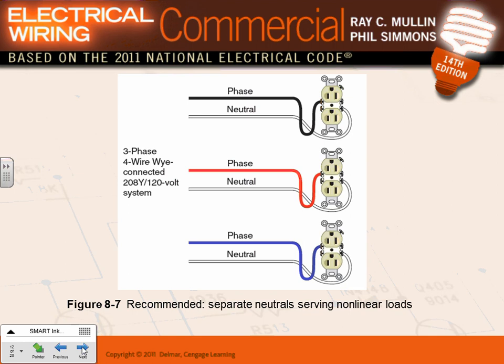So to eliminate the effect on the branch circuits, do you guys remember how we do that? We have a neutral with every phase. That's what you guys are doing with me, right? In this project, there are certain receptacles in that Revit project that require you to have a neutral with every circuit. Why? Because if you have 10 amps, they don't add up to 0 amps because there are harmonics on them. They might add up to 20 amps and overload the neutral. To solve the problem on a branch circuit like this, you just have a neutral with every phase. Can I have a thumbs up, Chad? Same thing when we do gas lights, a neutral with every light. So that solves the problem.